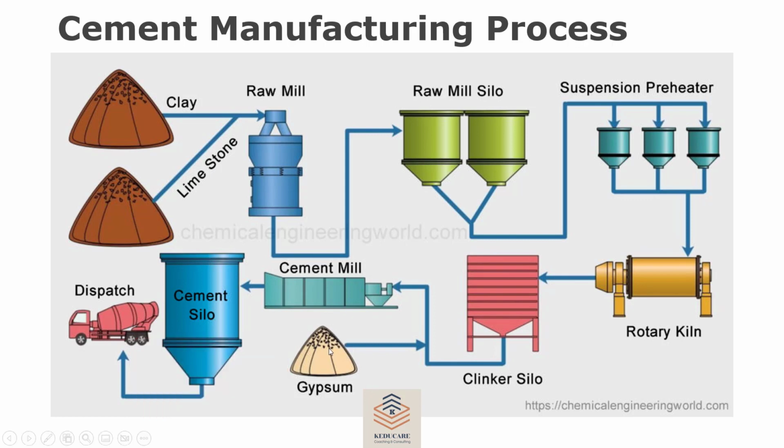The function of the gypsum is to retard the cement from setting quickly when it comes in contact with water, so that whoever is working with the cement has some time to place it properly where it is wanted, and to harden and shape it.